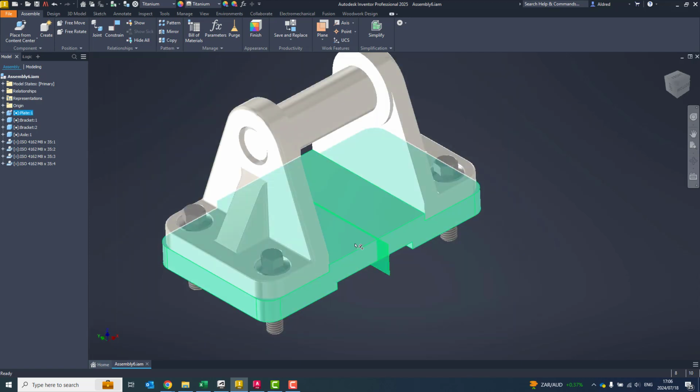But I don't want to necessarily change this base, because if I do, I'm going to have to change the part number, and if this base is sitting in other assemblies, then it needs to be updated in that as well. And if I do change this and it is linked to other assemblies, that will cause an issue.